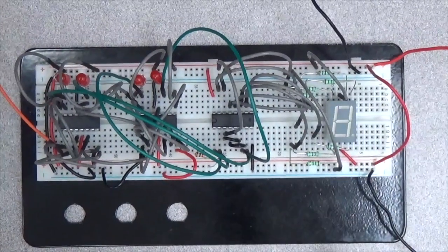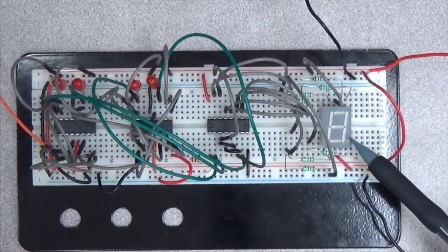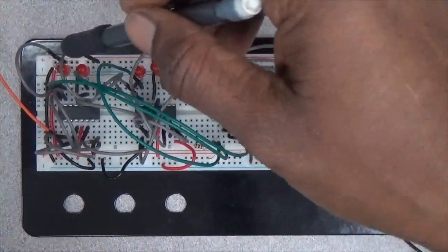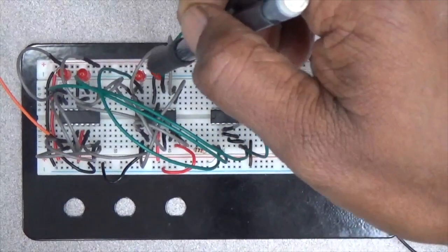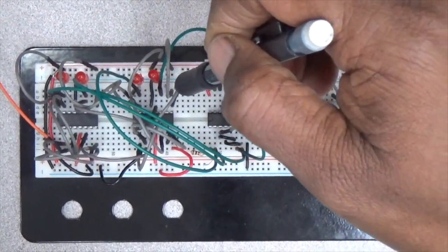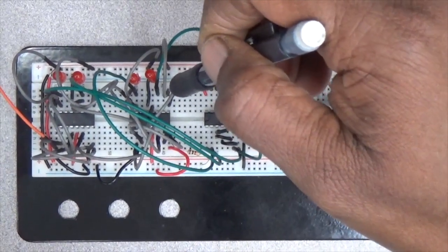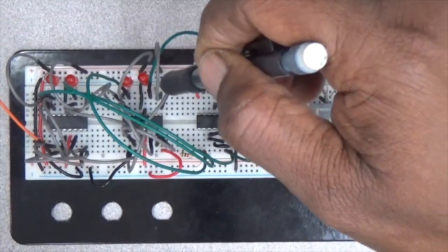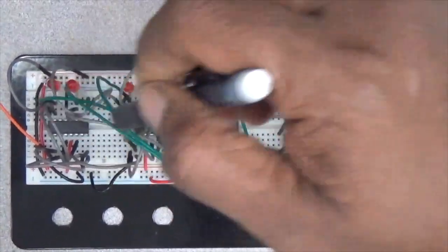I have hooked up the circuit. This is the 7-segment display that can count from 0 to 9, and I have also mounted the LEDs from those same pins 15 and 11, 15 and 11 to show the outputs from 1010 to 1111, like count 10 to 15 could be through these LEDs.